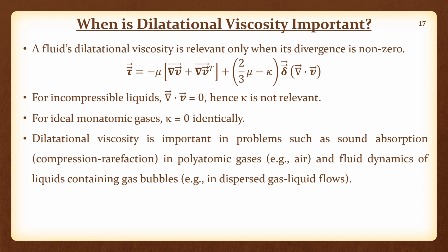So depending on the compression rarefaction, the frequency and the intensity of it, the audio that you are hearing is going to vary. And this compression and rarefaction or expansion of polyatomic gases in sound absorption is a problem where obviously del dot V will not be 0 and therefore dilatational viscosity of air would be important.